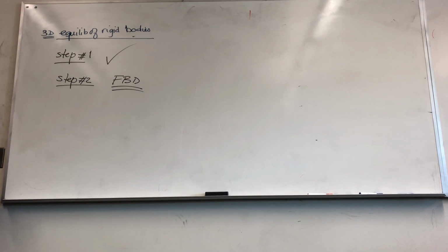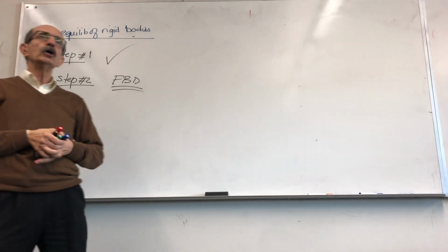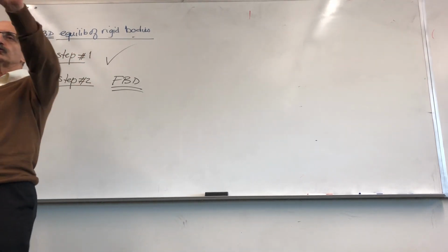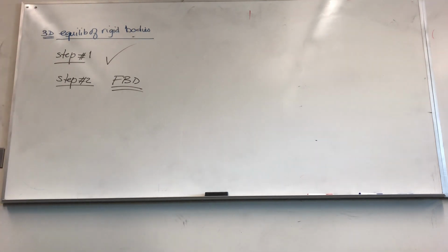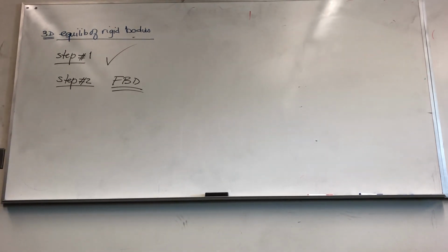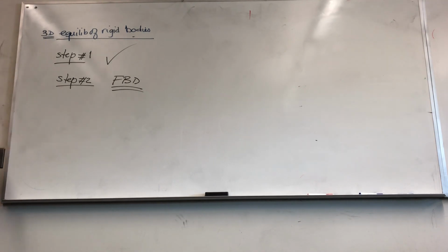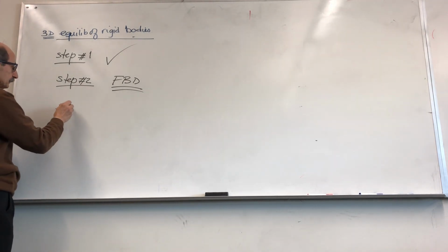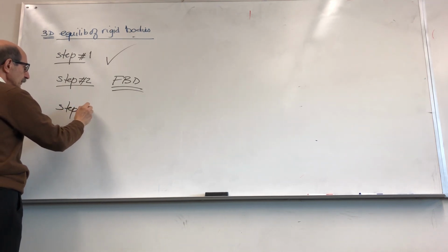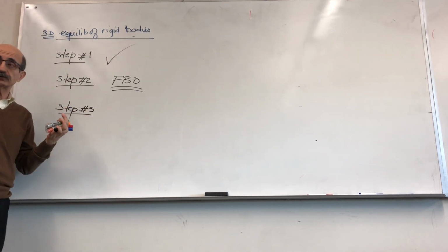And typically you are given either enough information or you're directly told that, for instance, on joint C, there is only one unknown, or this joint C does not allow motion in the X direction. Usually, either implicitly or explicitly, you're given that. So you set up the free body diagram. And the third step, number 3,